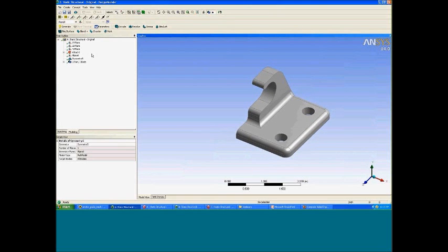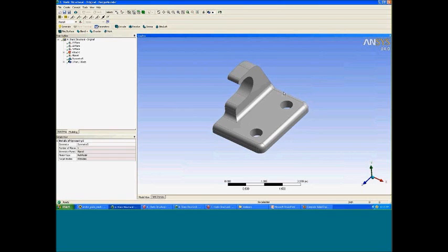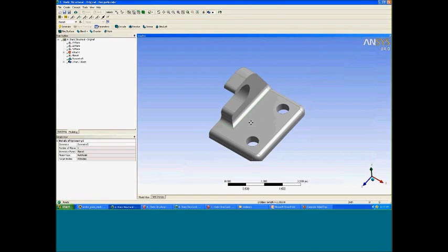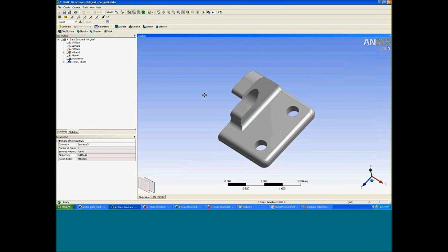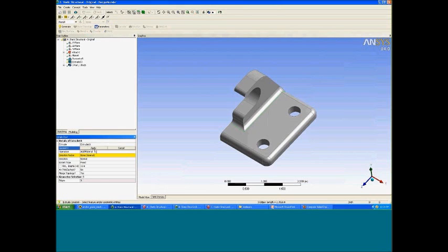Now, the first step in my slicing and dicing, what I'm going to do is separate this base plate from the chunky hook region. So the way that I'm going to do that is select these edges here, right around the joint, the area in which the base plate meets the hook region, and I'm going to highlight those edges and then go to the extrude operation.